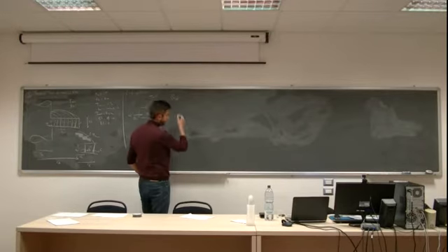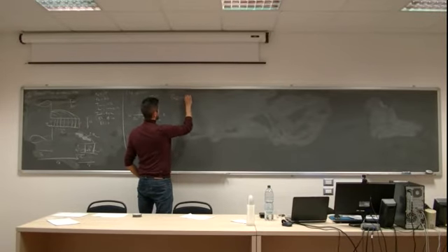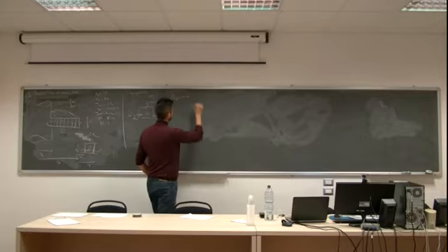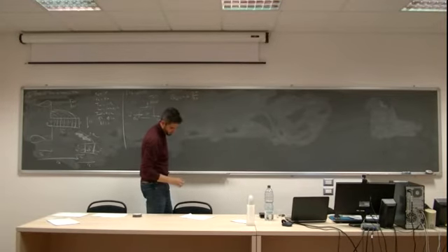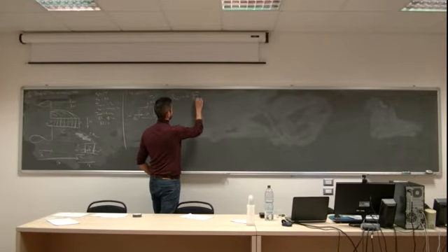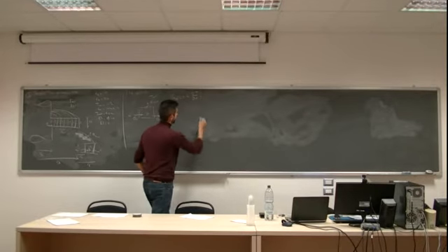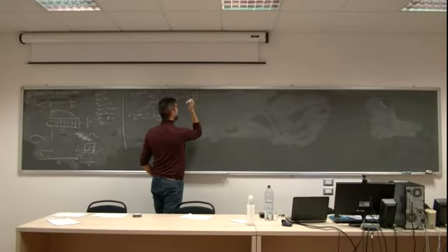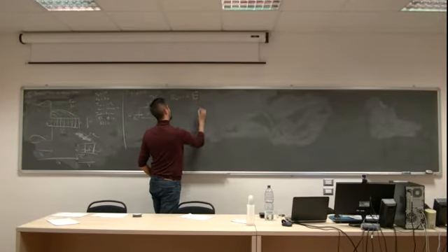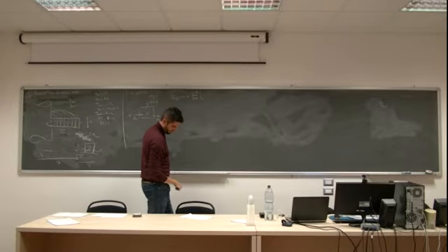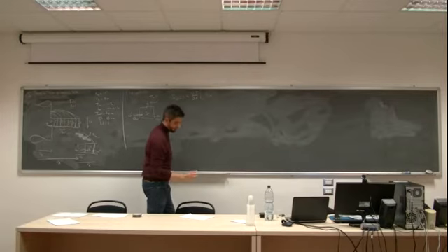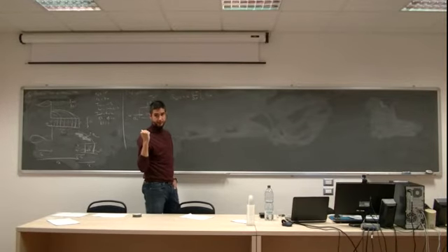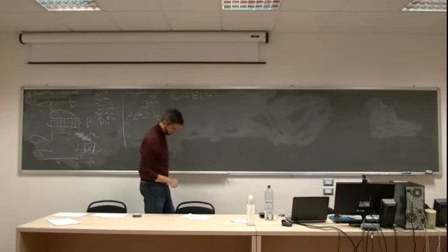Now, this is minus thermal conductivity of the fin, times the derivative in the space of R of the temperature. Where do we calculate this derivative? In the boundary of the west. Multiplied by the surface at the west that we have already computed in step number 2, right?